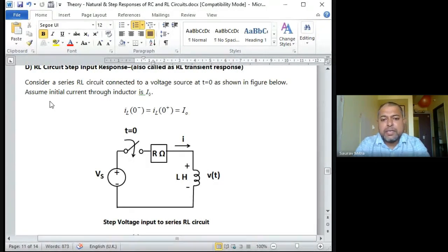If we take 200 hertz sampling frequency, we get only 2 samples. Then when you reconstruct, there are 3 steps. First, we take the frequency, then we sample it, and after sampling, we reconstruct the signal in the digital domain. So whatever graph you are seeing in all the experiments, all are digital domain outputs.